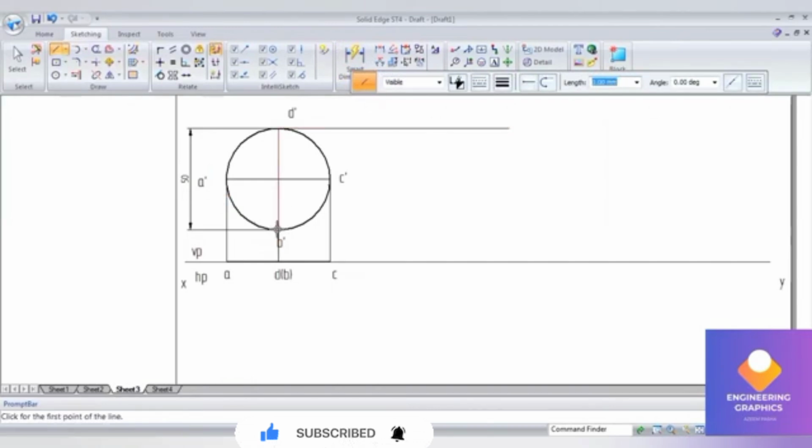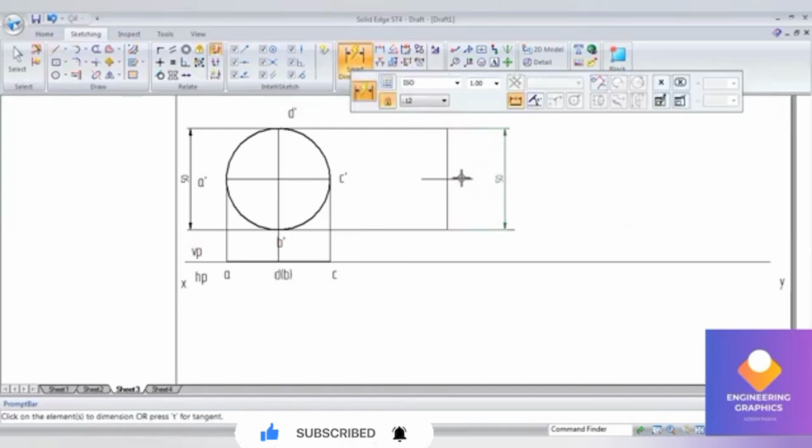from these end points. I'll consider major axis as 50 mm. From the middle point, for the minor axis I'll consider 25, means from one end I'll consider 12.5. The same way from that middle point other end again 12.5. Now I'll just show the major axis dimension and minor axis.